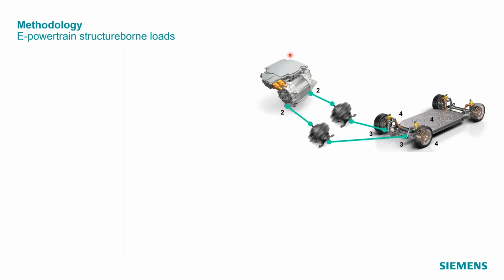Imagine that you are interested in characterizing this E-powertrain from the rest of the vehicle. You want to describe it as a component that you can use in some virtual prototype later on. Let's first consider how this powertrain is mounted to the rest of the assembly, because of course, powertrains are typically not directly rigidly connected to the body of the vehicle. In general, there will be some soft mounting solution in between that has the objective of isolating as much as possible the vibrations from the powertrain to avoid any negative response inside the vehicle cabin.